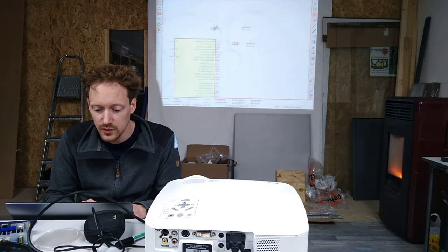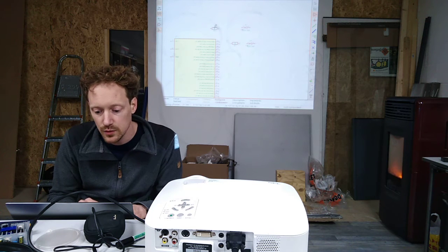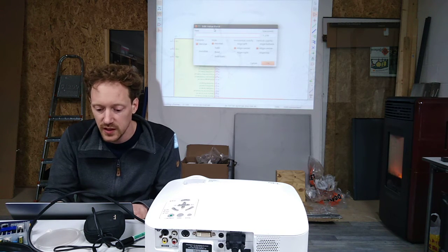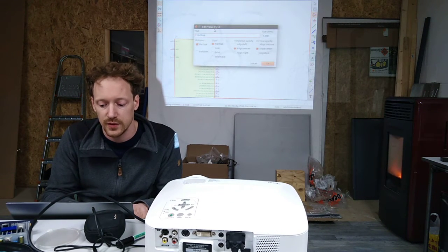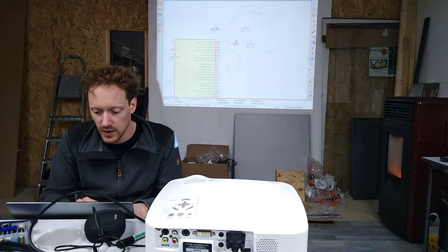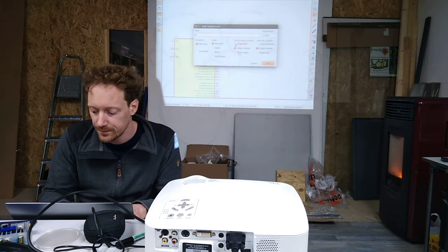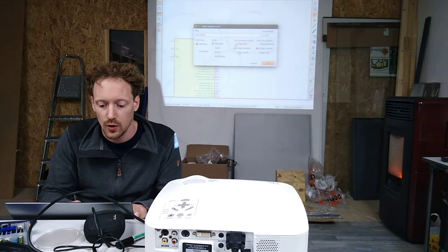And for the resistors, we could also give it a value, and here we press V, I would give it a value of 220 ohms. And do the same for this one, 220 ohms.